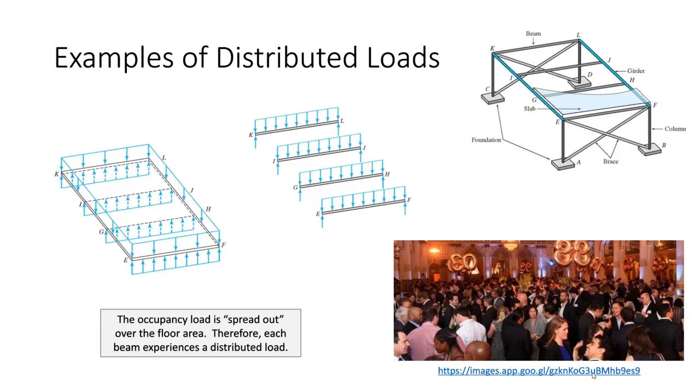So this is a very, very common means of developing structural models. This is also the way that we handle self-weight. Every beam, I don't care what it is, must be strong enough to withstand its own self-weight. And self-weight is more often than not modeled in a pounds per foot type scenario.